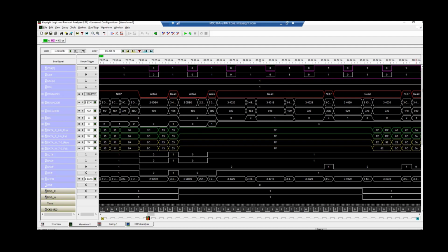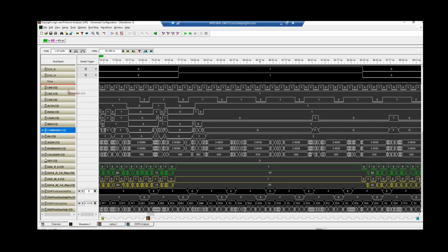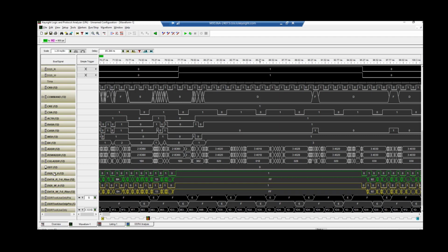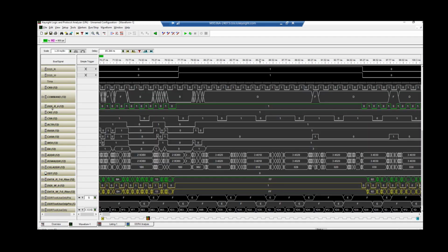As we scroll down now to the timing zoom, here we can just put the signals of interest, which is going to be the clock, the command, and the DQS. It doesn't really matter in timing zoom whether we're looking at read or write DQS because they're actually the same signal. Timing zoom is a small window, sampled at 12 gigahertz around the trigger point.